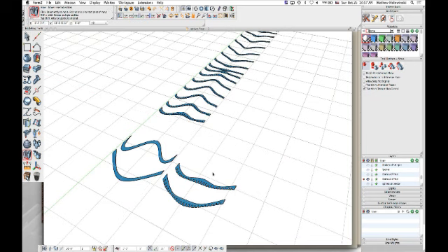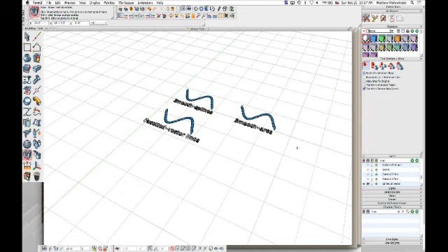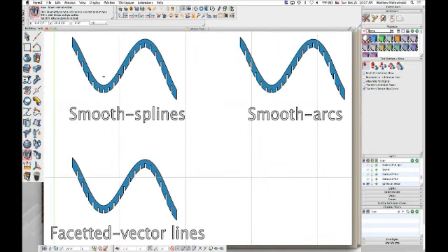Now, one last thing I want to mention about the CNC cutting is CNC cutters are expecting a certain type of geometry. And so you have to conform to what that CNC cutter wants. And so Formsy supports them all. Just to show you, if I were to look at a top view here, you can see that since we started off with NURBS type geometry, it's smooth spline-based data. When we cut our contours, the contours is spline-based mathematical data. Some CNC machines understand that, some of them don't.